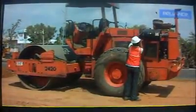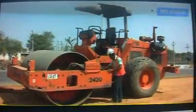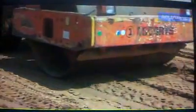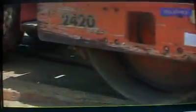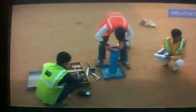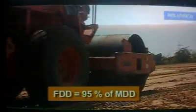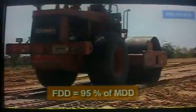The compaction is done with the help of vibratory roller of 80 to 100 kN static weight with plain drum. Each layer of the material is thoroughly compacted. Each compacted layer is finished parallel to the final cross section of the embankment. Successive layers shall not be placed until the layer under construction has been thoroughly compacted to the specified requirements and tested for field dry density. Rolling shall be continued till 95% of the maximum dry density for the material is achieved.